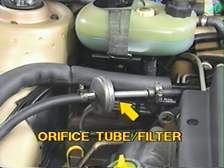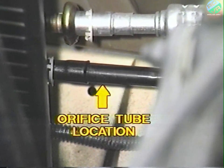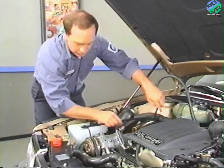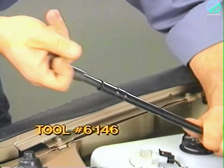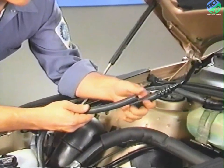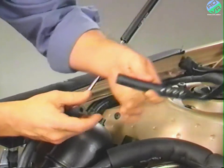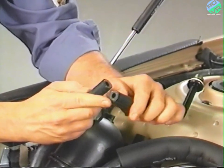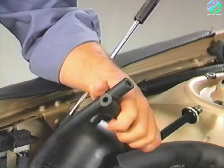To install the orifice tube and filter, you'll need to first remove the old orifice tube. So after discharging the system, disconnect the liquid line spring lock coupling at the condenser outlet. Then remove the orifice tube from the end of the line using tool 6146 and reinstall the line on the condenser. Next, cut a 5-inch section of hose out of the liquid line between the condenser and the evaporator. The cut must be made in a straight section of line close to the evaporator.